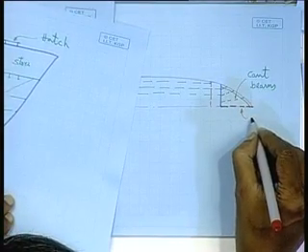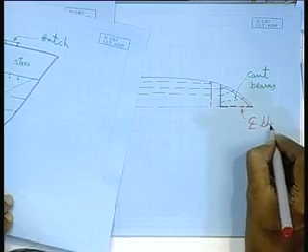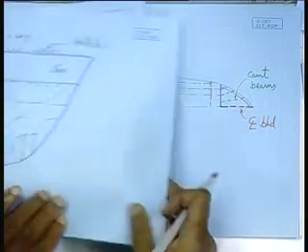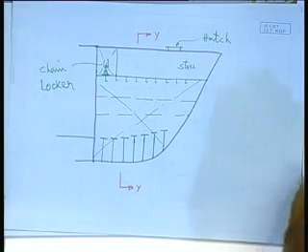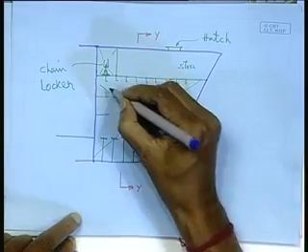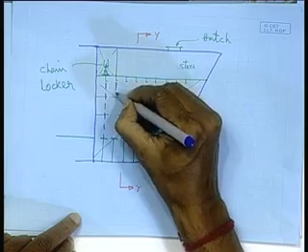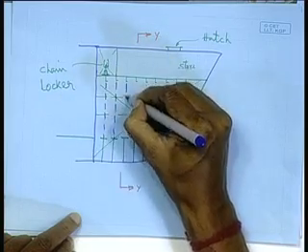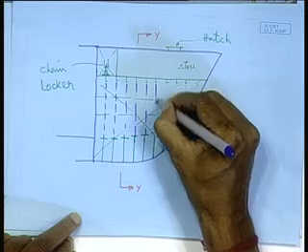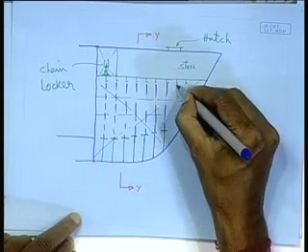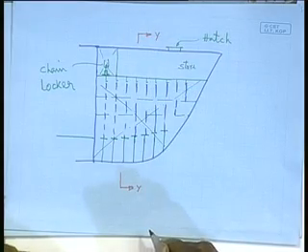That means, provided a centerline, by centerline bulkhead we mean a full plate. But obviously the plate we are keeping will have its stiffeners connecting from the beams to the floors. So this will be a longitudinal member.